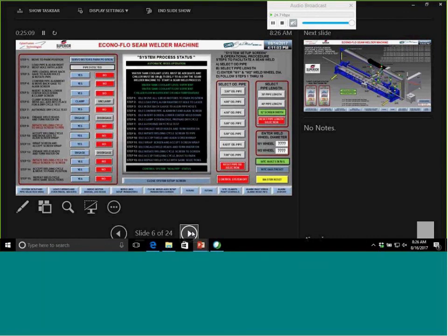And then we do the self-centering and the automatic clamping through a couple axes on the back. And then once the machine is set up, we have what we call an automatic dry cycle. And at this point, we'll run the machine down without welding to ensure that everything is fine, nothing crashes, and we've got the right amount of pressures applied to the heads, and we're coming in at the correct angle.